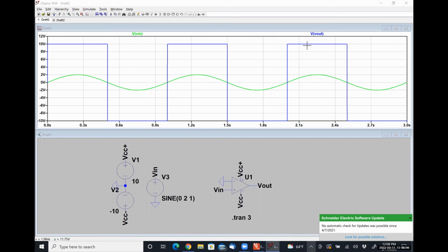And you do not need a resistor to the supply, because the op-amp is operating anyway. There is going to be some current, but it's going to be incredibly small. If we are putting a 2-volt signal, that signal is effectively being applied over a resistor on the mega ohm scale, which means it's drawing microamps of current if it's a BJT related device, or picoamps of current if it's a MOSFET related device. So not enough to really matter. So the resistance in the op-amp is all that's needed. Exactly right.